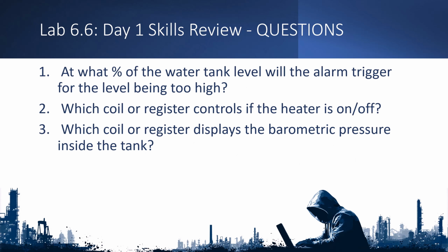And with that water tank, there are a couple of questions that you answer. At what percentage of the water tank level will the alarm trigger for the level being too high? Which coil or register controls if the heater is on or off? And then can you manipulate that to turn the heater for the water tank on or off?